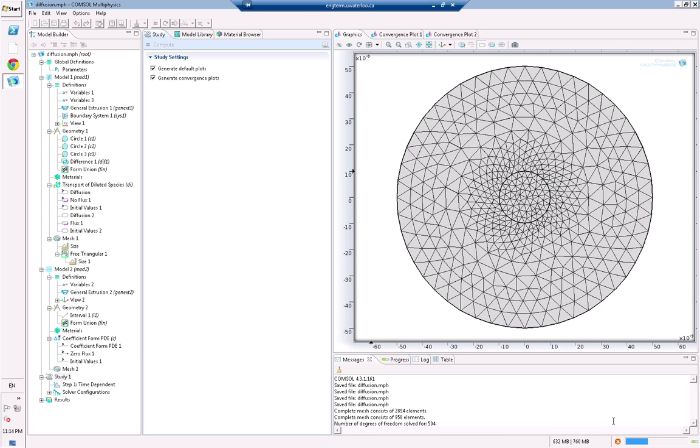If the computing of the model is really time consuming, what you can do is increase the step size in the study. So right now the step size is equal to 0.1 and we are calculating the model from 0 to 1000. If you increase the step size to 0.5 or 0.2, then the calculation time will be less.